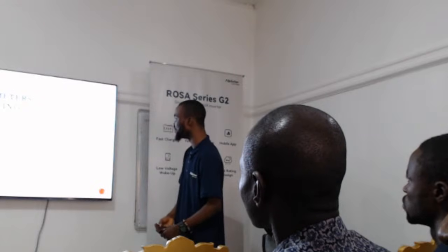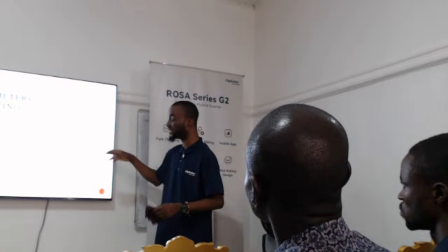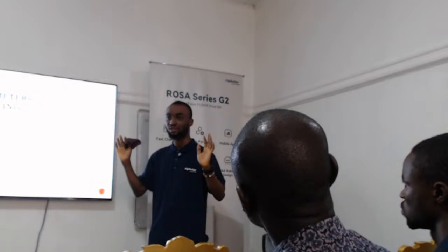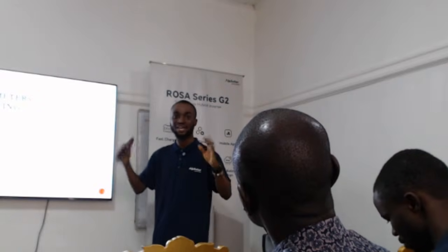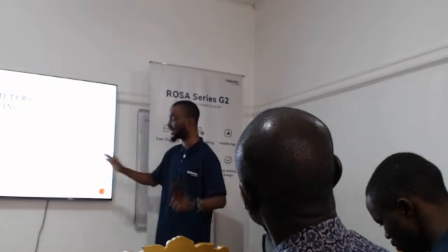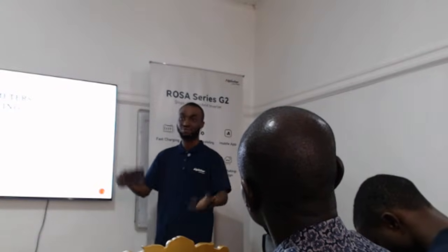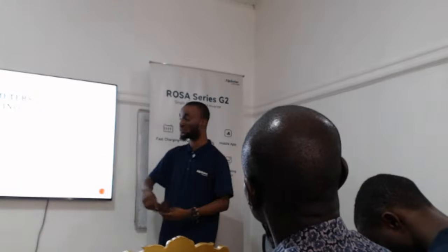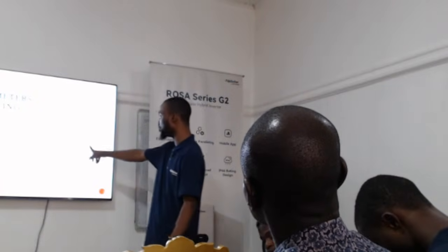Battery automatic activation: if you want to be using this key to switch off your battery, you can set it here. There's a way you can set this inverter so that anytime the battery is on, it will come on. This is battery automatic activation. It will automatically come on anytime the battery is on. But if you don't want that, you can turn it off. The default is always on. That's why you notice that you have not switched on the inverter, but the inverter is on because you have switched on the battery, because the battery automatic activation is always on.